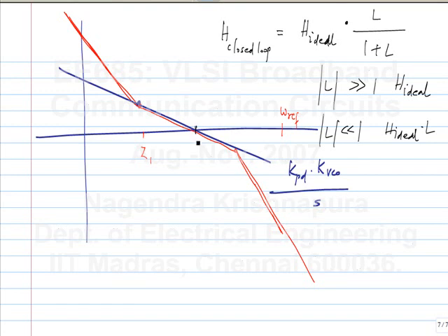overall transfer function, okay. So essentially if this is the loop gain, below this point, if it's a unity gain feedback loop, the gain will be unity, and above this it will simply follow this curve, okay. So if this was a unity gain feedback, the closed loop gain would look like this. So again, using the loop gain you can plot the closed loop gain, okay. Now you want attenuation in the closed loop response, so you introduce attenuation poles beyond the unity gain frequency in the loop gain.